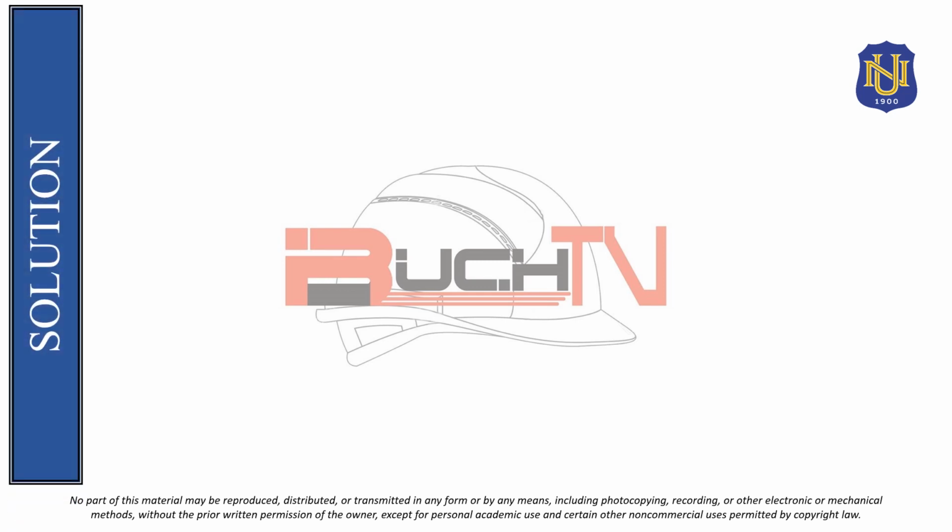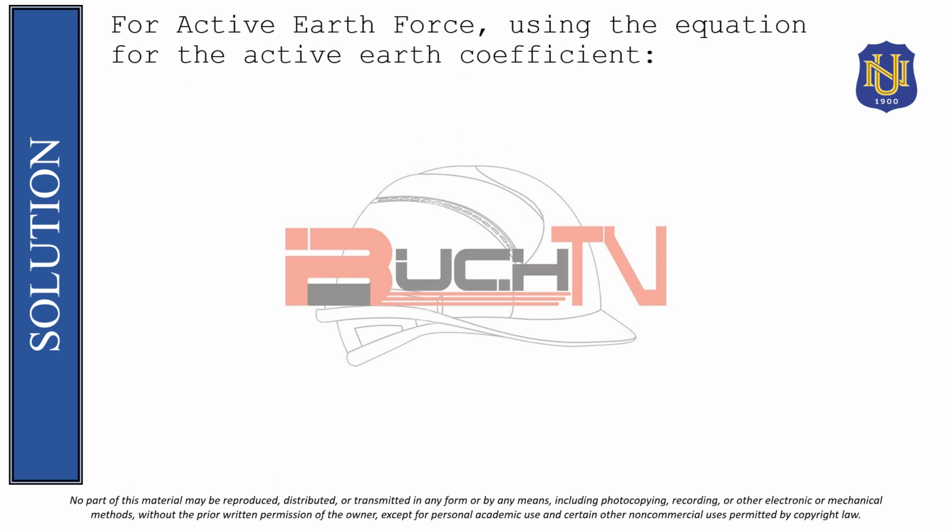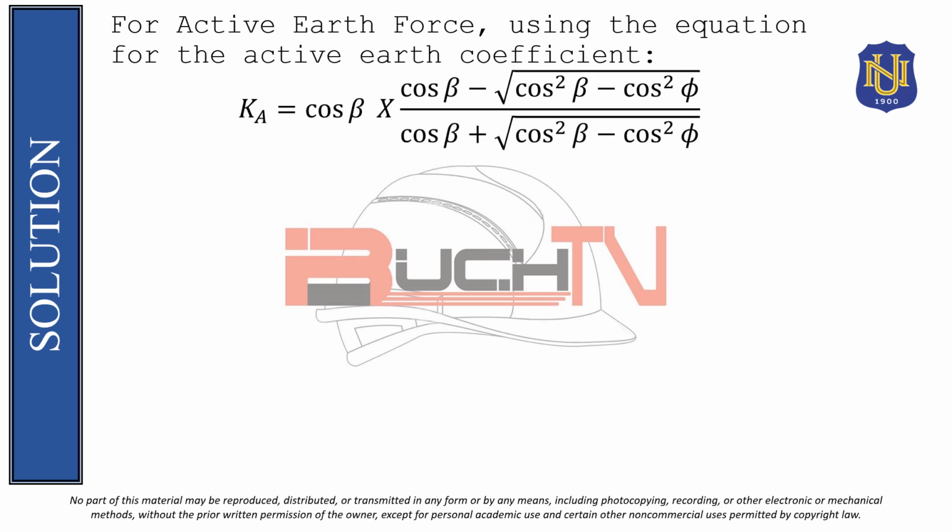For our solution, we will first get the active earth coefficient using the equation of Rankine for sloping backfill. So that is K sub A is equal to cosine of beta times cosine of beta minus square root of cosine squared of beta minus cosine squared of phi, divided by cosine of beta plus square root of cosine squared of beta minus cosine squared of phi.